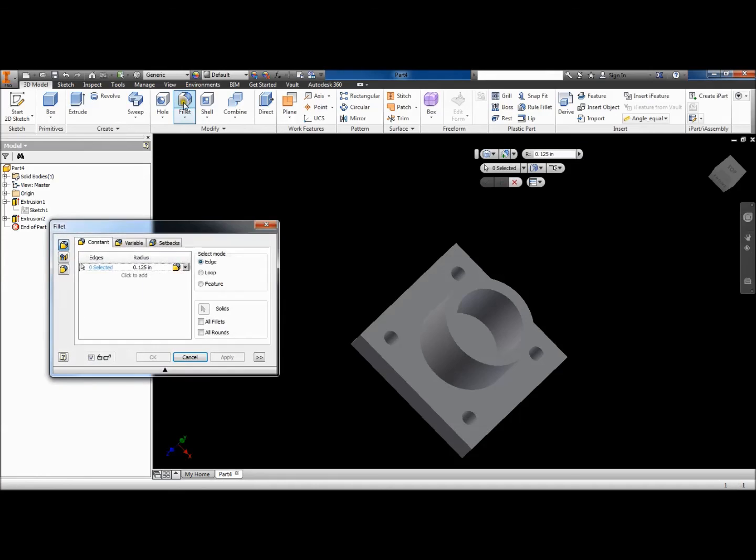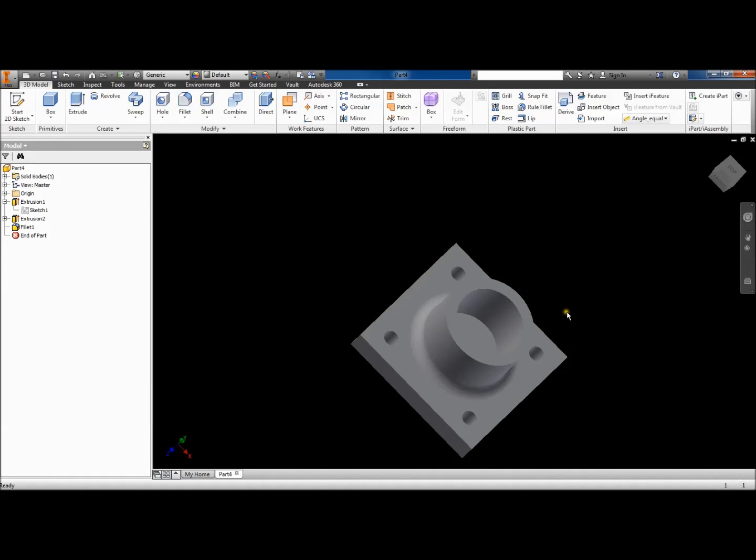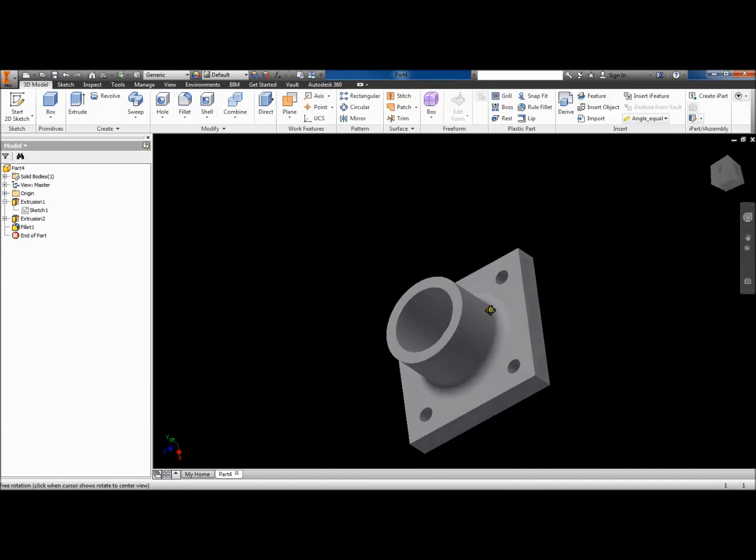We'll use the fillet tool, and we're going to do a fillet that is 3/8 of an inch and a constant fillet. And I will hover right here. This is where we want the fillet. So it's going to look like a weld. And so it has put that 3/8 inch fillet. Actually, it's 3/16. I erred. So I'm going to change that back to 3/16, and it immediately changes. So I will hit apply, and it is consumed, and I'll close the fillet tool, and voila, we've got the three-dimensional part.